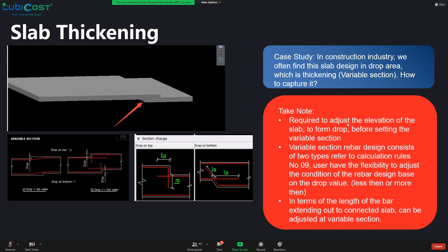Before I teach you how to capture it, things to take note of: you are required to adjust the elevation of the slab to form a drop first before setting the variable section. Because normally users will straight away jump to the set variable section and try to capture this design, but it will not succeed. Why? You need to form a drop first, then only go to the set variable section to form this shape.